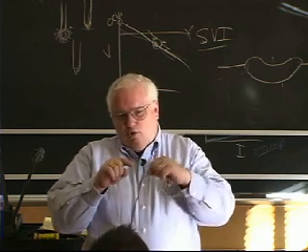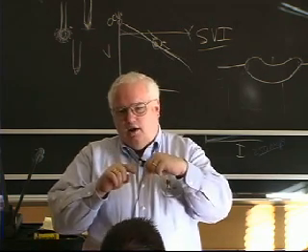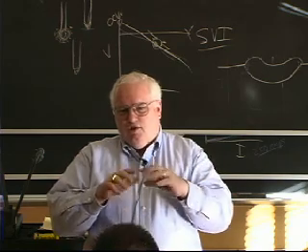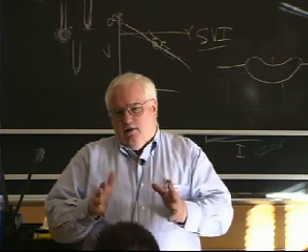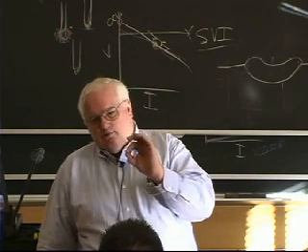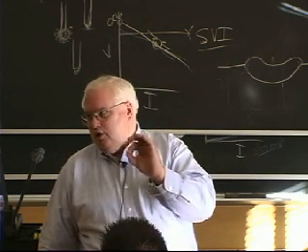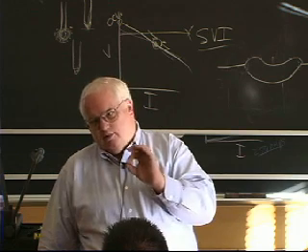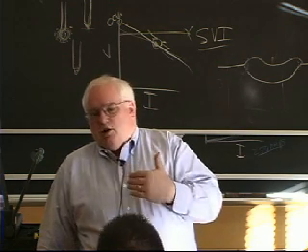You've got the weld reinforcement, so it's hard to see right there where it stops, the change in density of a 20 thousandths flaw in something that's 280 thousandths thick in this case. So it's hard to see it.